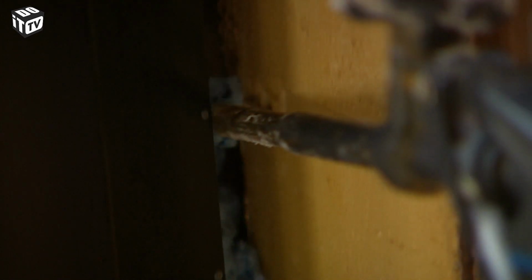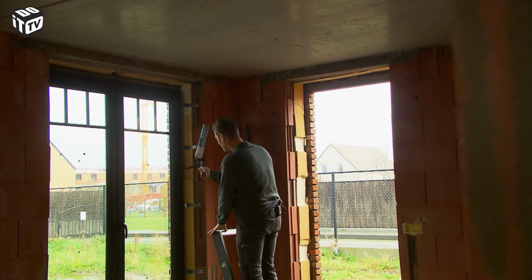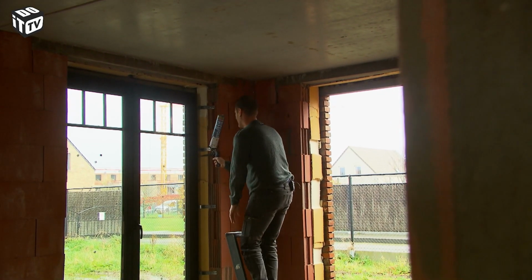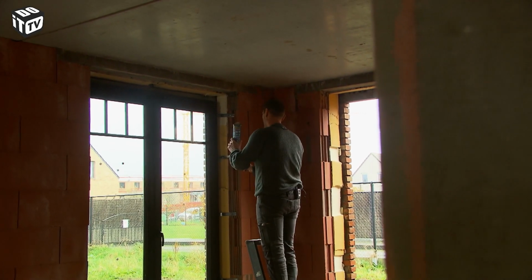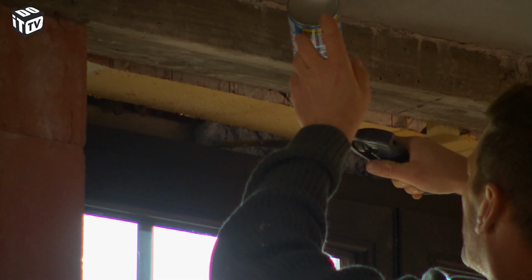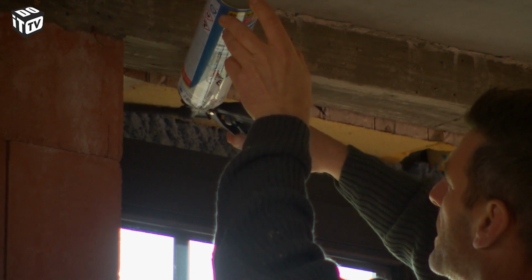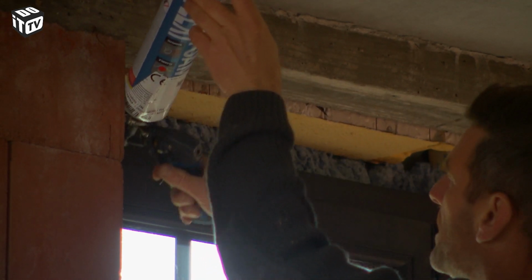When using high expansion PU foam, you first set a few dots that you let harden. Only then do you complete the necessary layer of insulation. The filling foam is water repellent and will also provide an extra attachment for the window. Be extremely careful not to get any PU foam on the PVC or aluminum joinery. If you can't immediately remove it with a correct product, you can damage the paintwork.